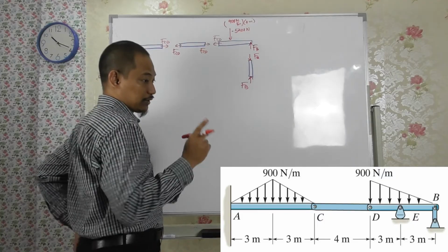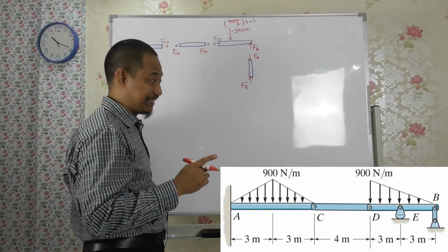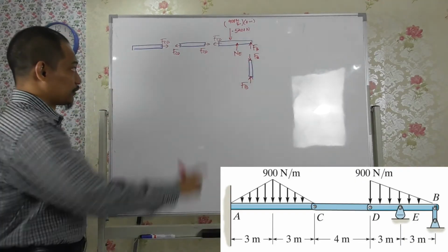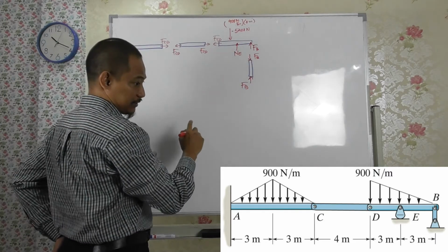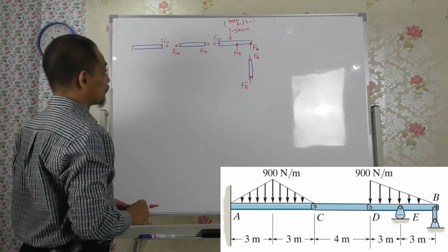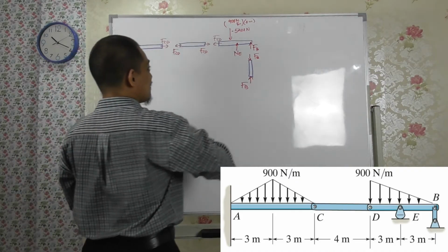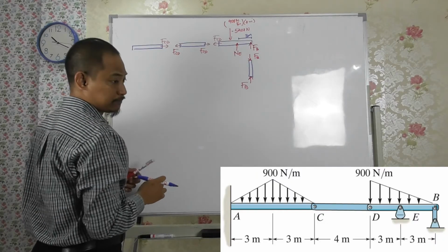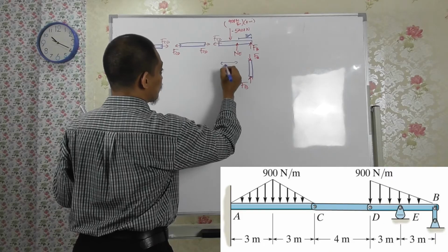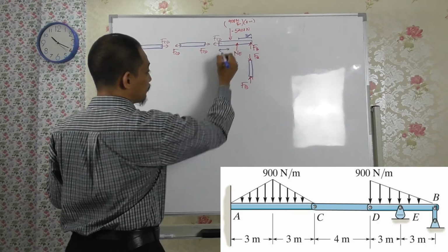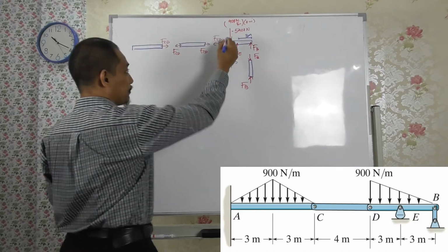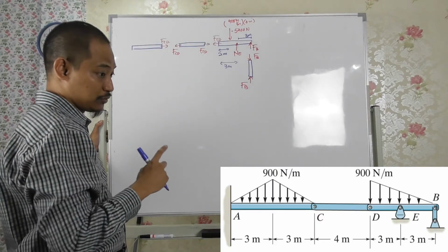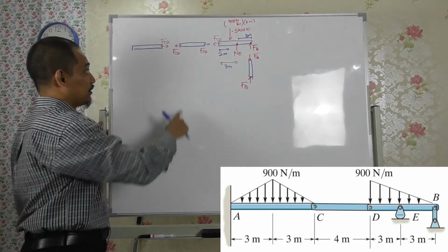But first, you have also another force there from the rocker at E. So you have an E, right? For the distances, you have 3 meter here. How to draw? Okay, let me use blue one. This one is 3 meter, right? This is also 3 meter, but to the force here, it should be 2 meter, right? Because the distributed loading is a 1/3, 2/3 ratio, right? So 1/3 is 2, 2/3 is 4, right? So that's there. This one is just a 2 force member.